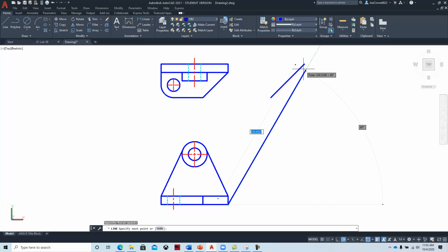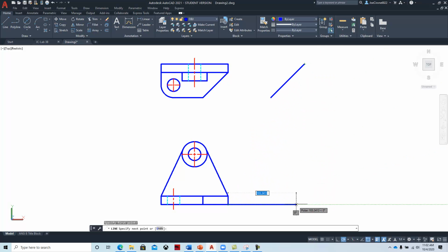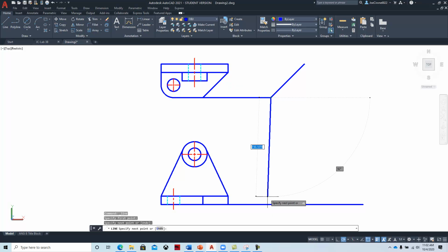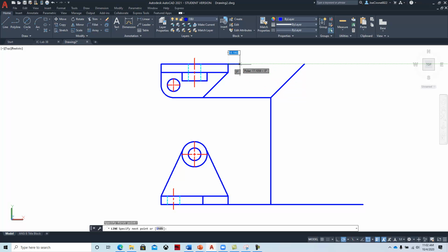And if you can't track these, and I'm having trouble kind of tracking them, as you can see, just go ahead and put them and extend them. So this would go from here. Let's do it the way I would do it with a pencil. So the way it would work would be to get the dimensions from the depth dimensions in the top view to the side view. What you would do is you would project them from this point here to this point here to here. And then we do that again with the back of the part.